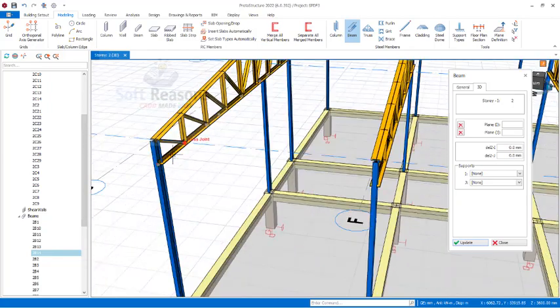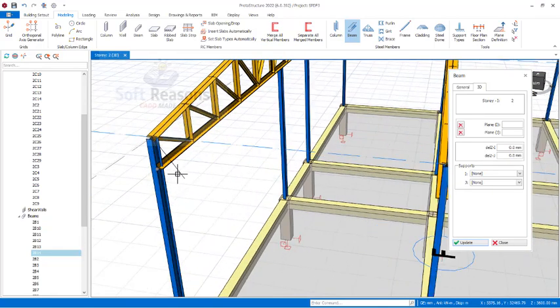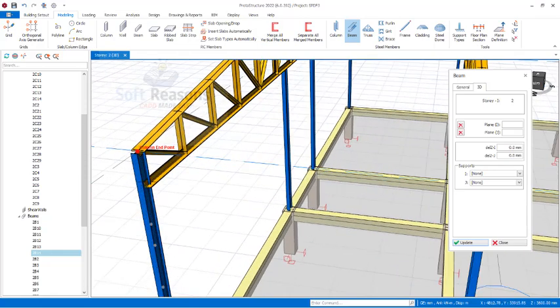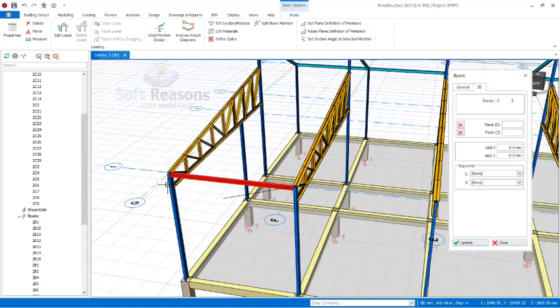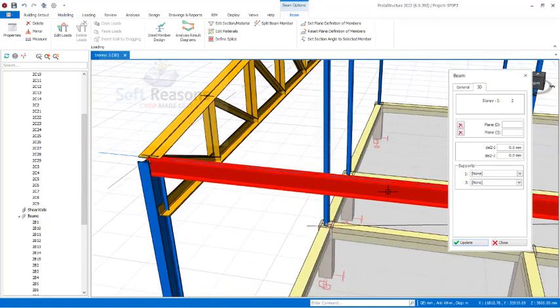There's another point from this point, but for the sake of these trusses here, we can still shift this a little bit downward. Click right there first, so during connection design it will not be clashing right there. For you to avoid that clashing, you have to send this down a little bit.